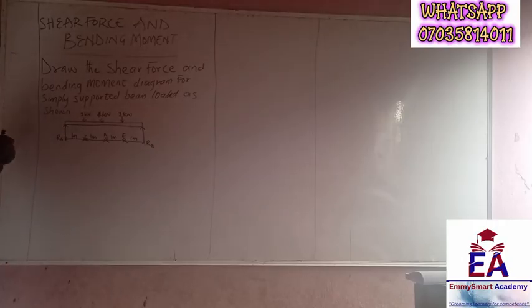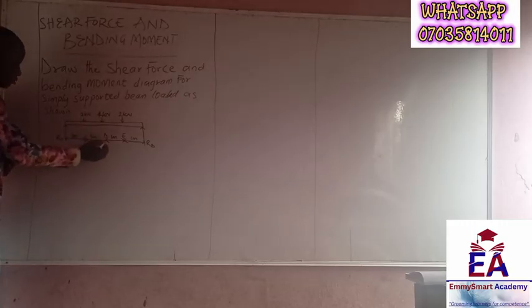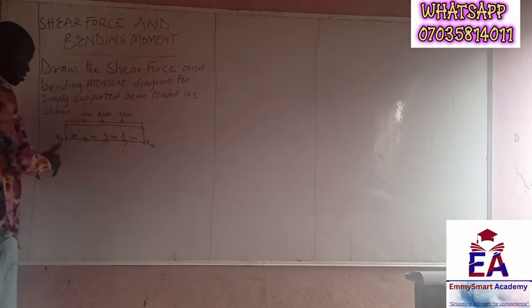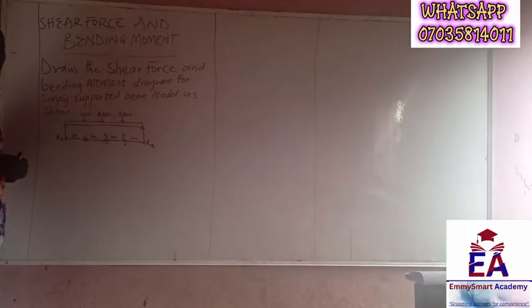Okay, we have to draw the shear force and bending moment diagram for the simply supported beam loaded as shown below. So we have 2 kilonewton here, we have 4 kilonewton, and then 2 kilonewton acting at several points on the beam. Then we have reaction forces acting at the ends, holding the beam upward, right? These two reaction forces are acting upward, while the other forces are acting downward. Remember we said that these are vertical forces.